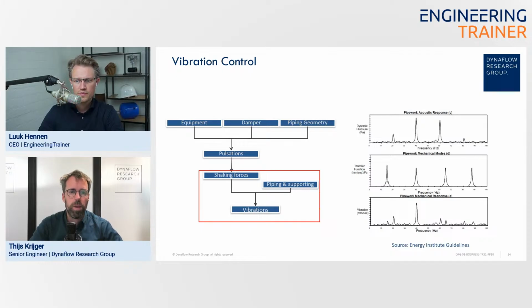I think it depends on how often the thermal cycles happen. If this is a low cycle fatigue thing, then probably you assess that in combination with your other static loads. If it's high cycle fatigue, then you have Miner's rule to combine different fatigue cycles together to assess damage.